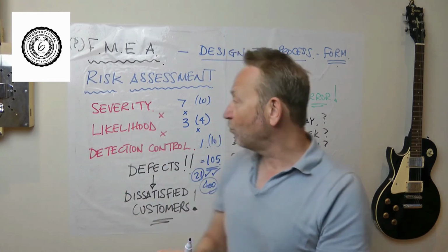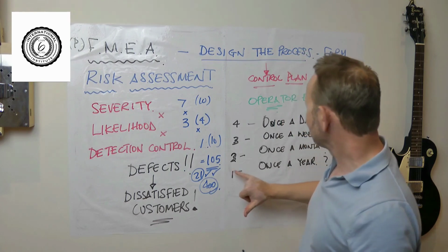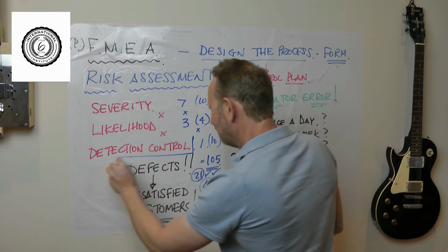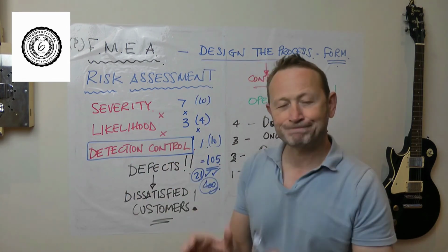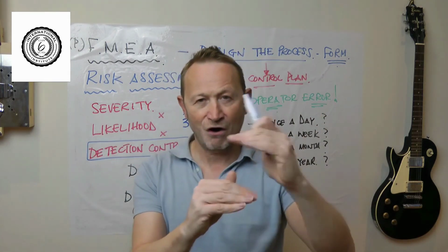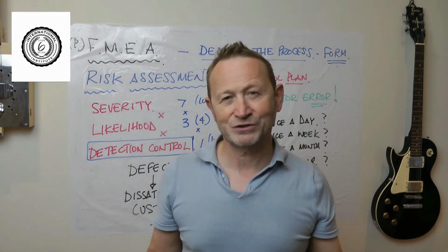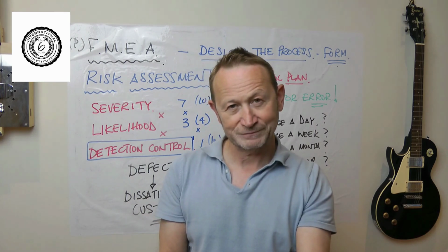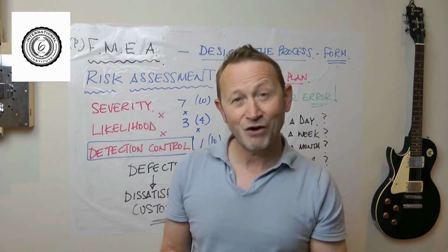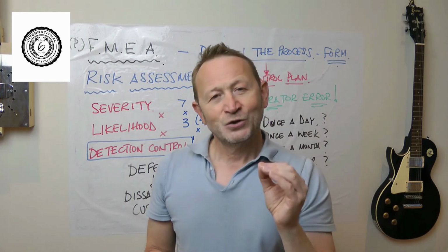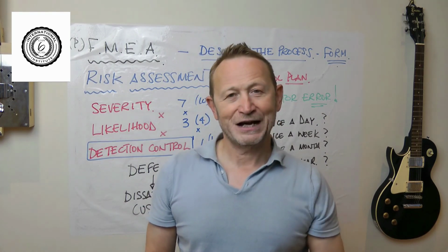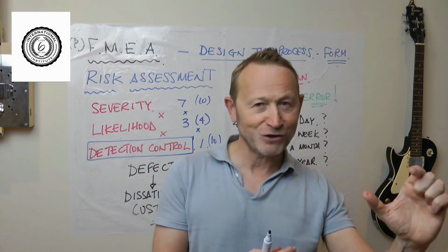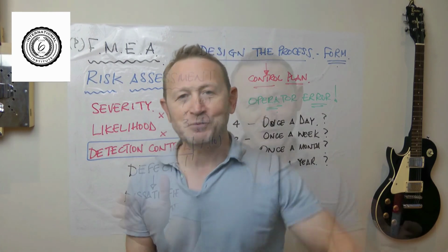But once you're ready, what comes out the other end? Well, what comes out the other end is a control plan. So on the end of this thing, where I'm saying I'm going to use timed locks on the dryers, that's a control technique. That's a control plan right there. In the planned control column, in this column down here, we have a control plan. And if you ever get a problem with your molding process, if you ever get a problem molding the battery cover, what do you do? You pull up the control plan.